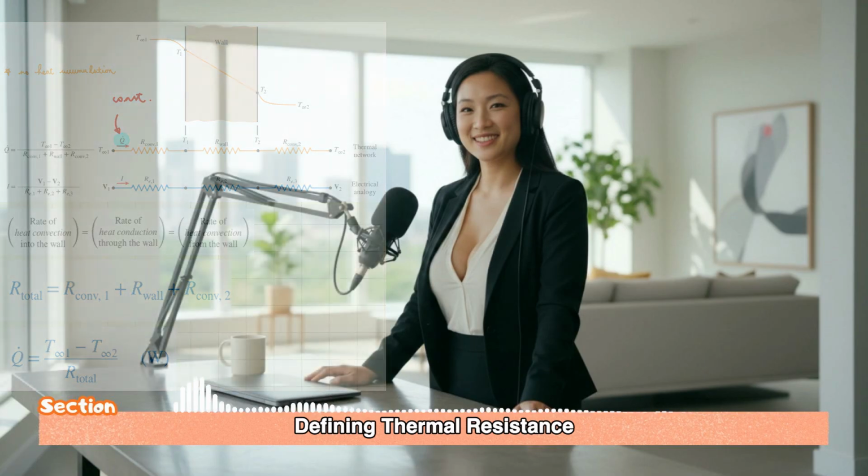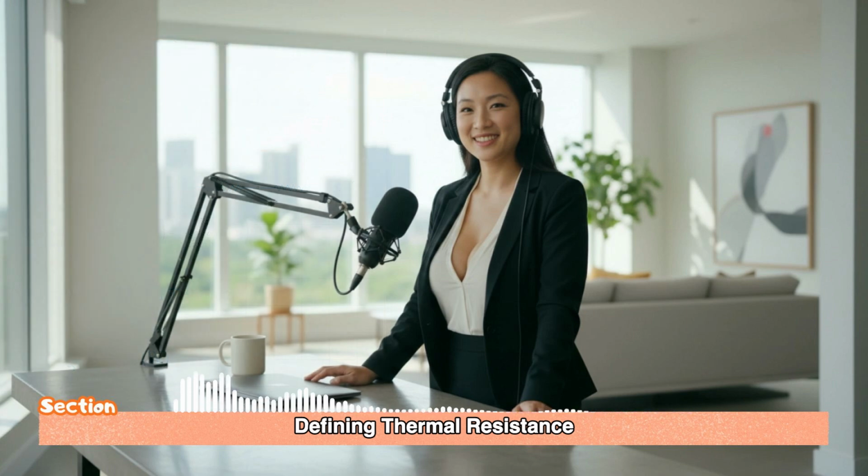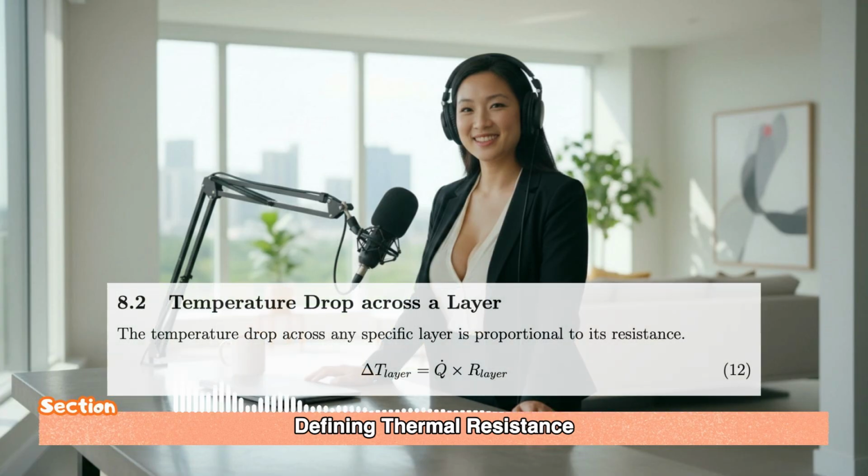Now here's where we can bridge the gap between the circuit diagram and that temperature profile we talked about earlier. How does the size of the temperature drop across a layer relate to its resistance? This is maybe the most crucial takeaway for an engineer because it instantly tells you where your thermal bottleneck is. Since Q dot is constant throughout the entire series system, if we just rearrange our main equation, we get the temperature drop across any specific layer. Let's call it layer i, as delta T_i equals Q dot times R_i.